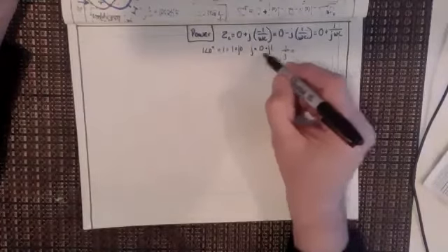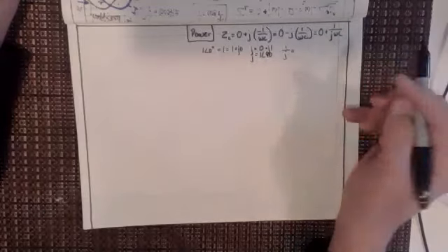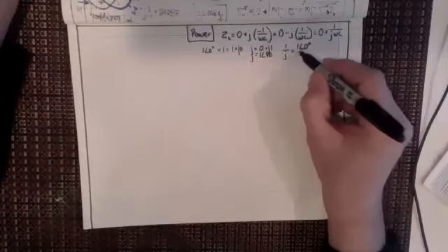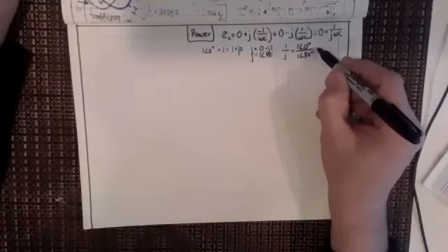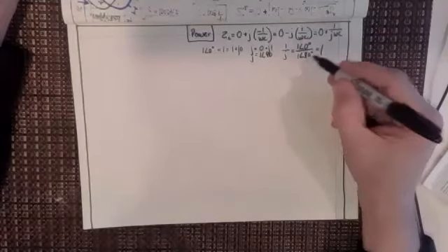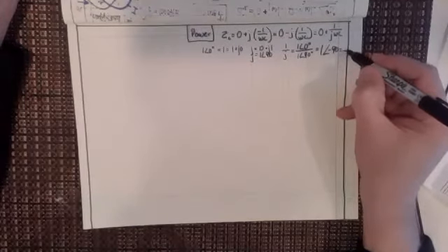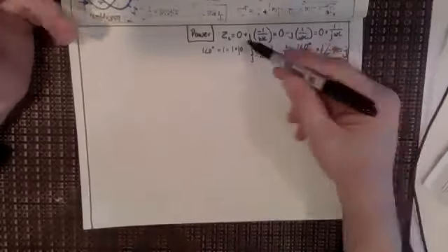And J, of course, would be 1 at an angle of 90 degrees. So 1 over J would be 1 at an angle of 0 degrees divided by 1 at an angle of 90 degrees. So what would that be? That'd be 1 divided by 1, which is 1, and then 0 minus 90, which is minus 90, right, which is minus J. So yes, 1 over J also equals minus J. Does everyone see that? And you would have to know that and have understood all complex numbers.